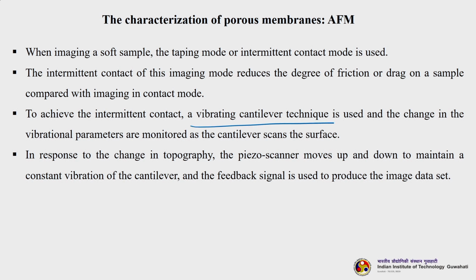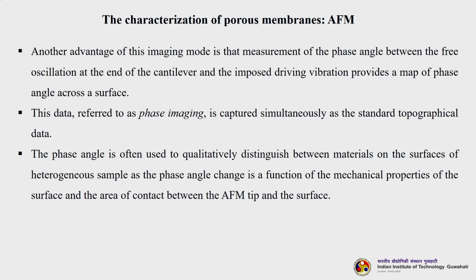In this technique, the cantilever is vibrating, and changes in its vibrational parameters are monitored as the cantilever scans the surface. In response to changes in topography, the piezo scanner moves up and down to maintain a constant vibration of the cantilever, and the feedback signal is used to produce the image.